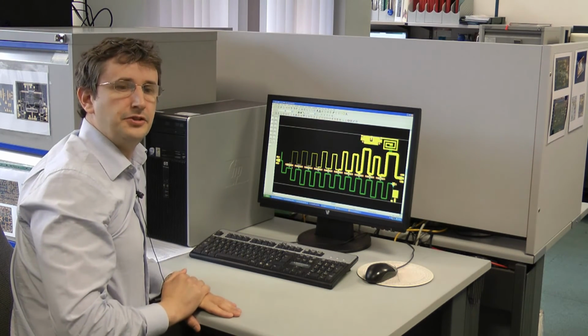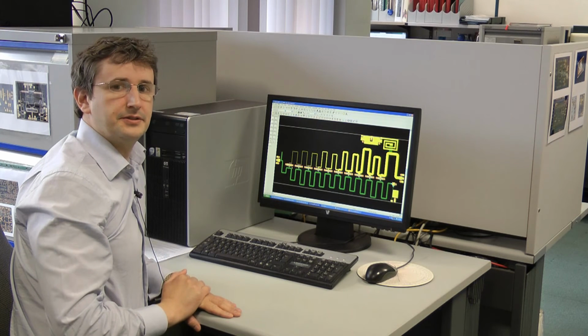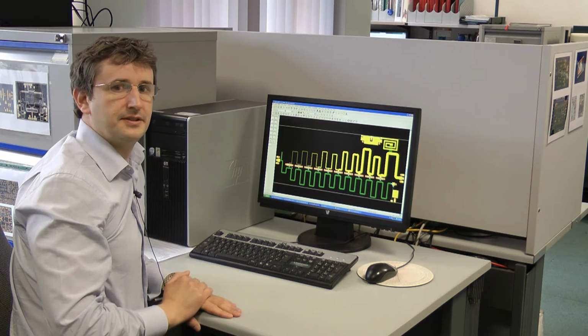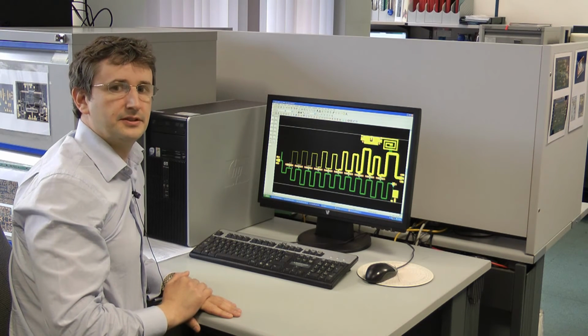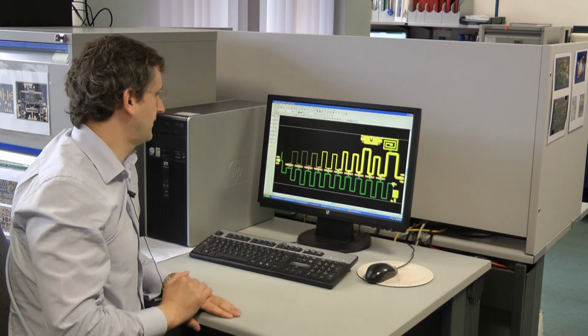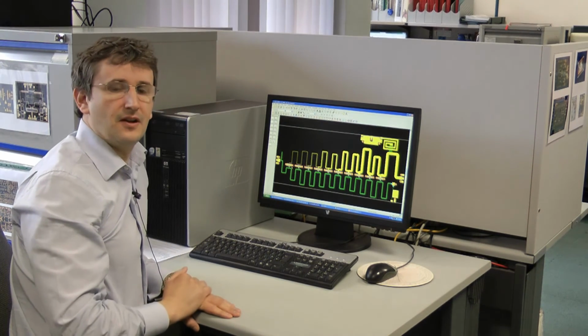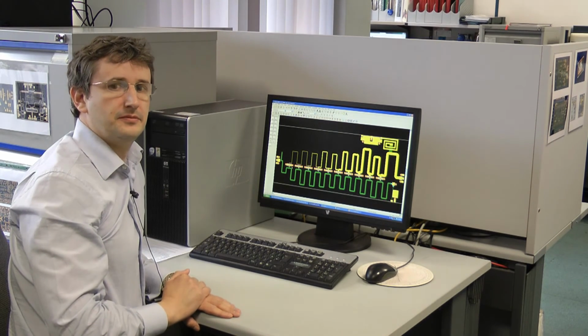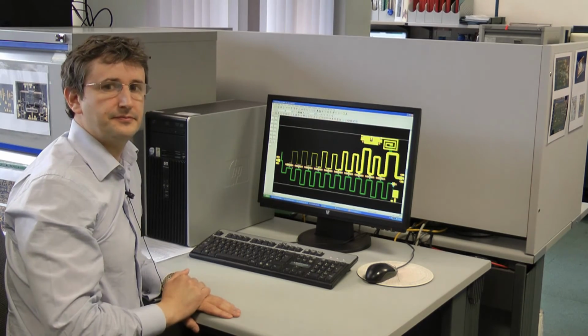This reduces the required load resistance at this point, enabling us to realize this thin microstrip line without breaking the process design rules.